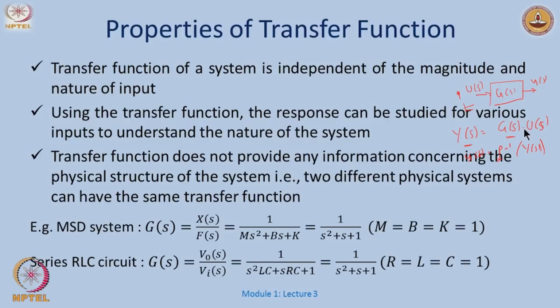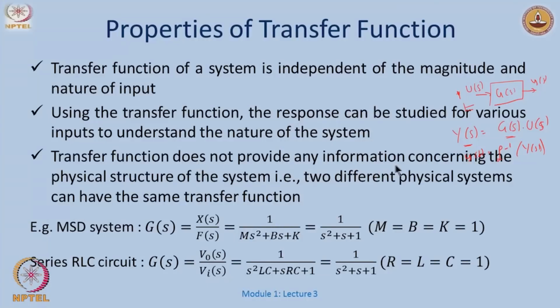Well, now is a transfer function unique? So, give me a transfer function, can I say what kind of a system it is? Can I say is it a car, is it a bus, is it an aircraft or whatever? Well, the answer is no. The transfer function does not provide any information concerning the physical structure of the system, which means that two different physical systems can have the same transfer function.